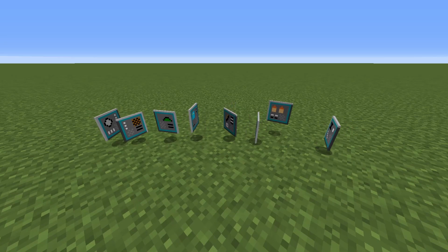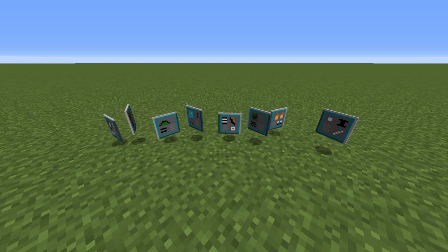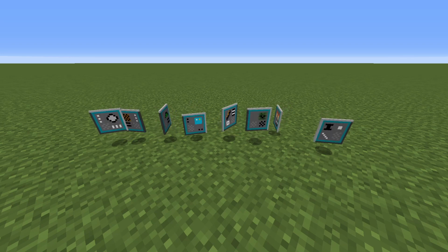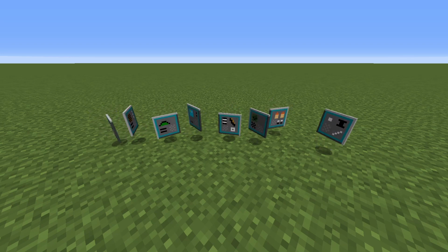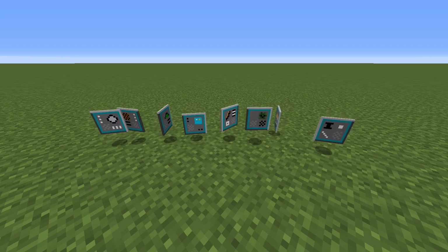Keep in mind that any dimensions with the exact same dimlets in them will be linked, meaning a new dimension will not be created. If you want to create a new dimension with the same dimlet as another, you'll need to use a digit dimlet to make the dimension unique.